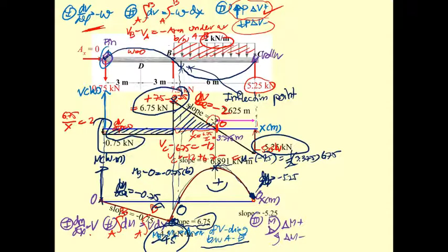negative. It's also important when you put the reinforcement into the beam. For example, for this one, if you'd like to put the reinforcement, let me put it in green. For the positive moment, you put this one like this.